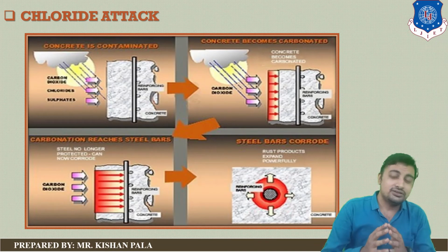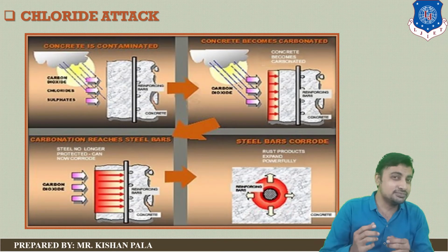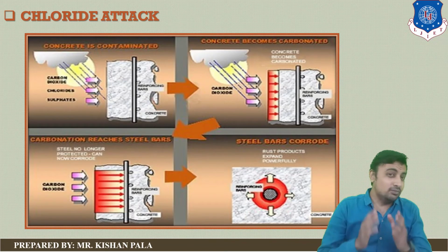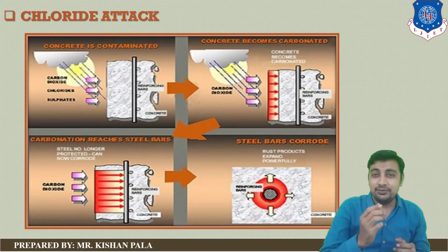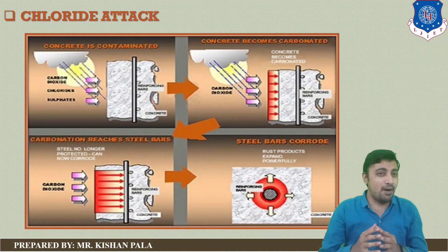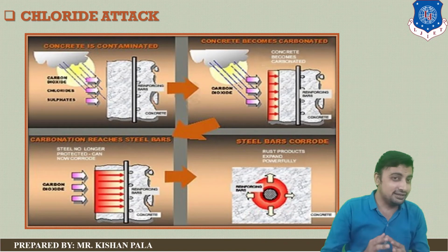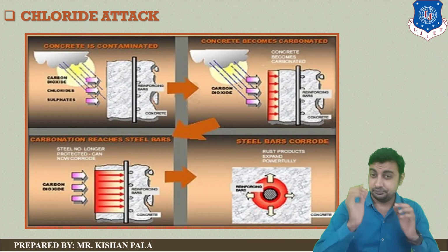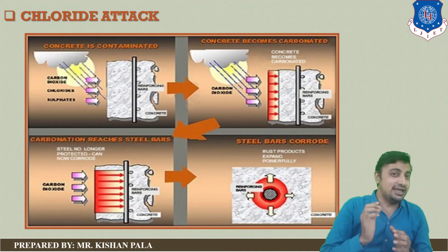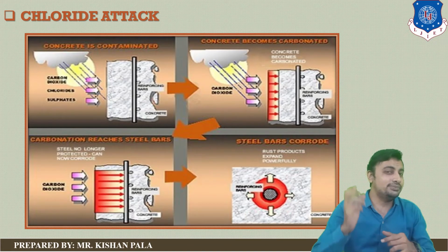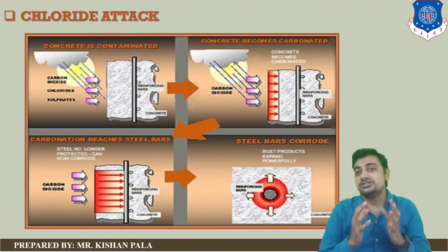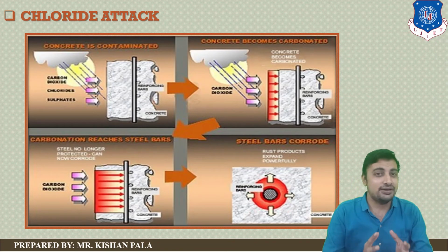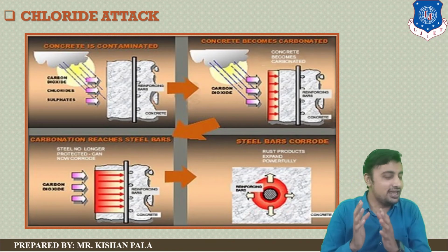As more ice melts, the melt water becomes diluted until its freezing point rises to near the freezing point of water, and freezing takes place again. This increases the number of cycles of freezing and thawing and promotes the corrosion of steel. So this is the effect of de-icing.